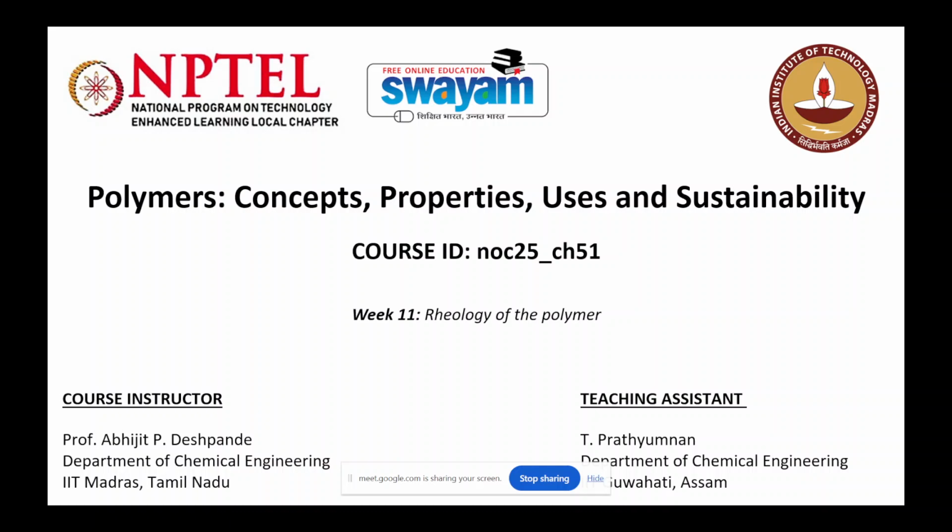So, since we are discussing rheology and we need to see how polymer systems behave, we are going to come up with models to understand their behavior. Usually these models are classified based on the energy storage or the energy dissipation, that is, storage modulus and loss modulus.